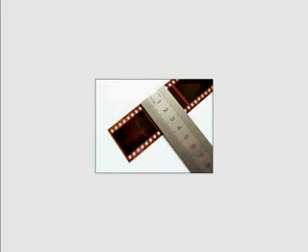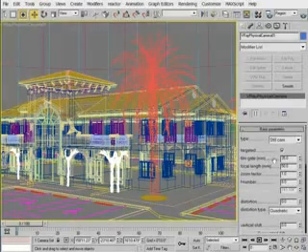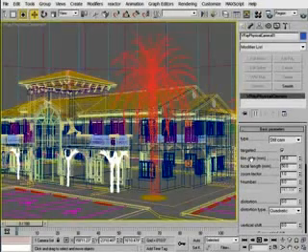So when you hear things like a 28 millimeter lens or a 300 millimeter lens, don't confuse this with film size, which by the way is also a setting found within the VRay physical camera. I recommend leaving this particular value at 35 millimeters because this has long been the norm in photography.